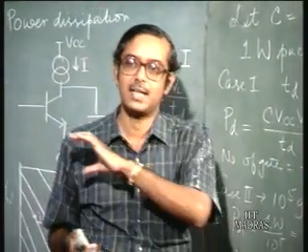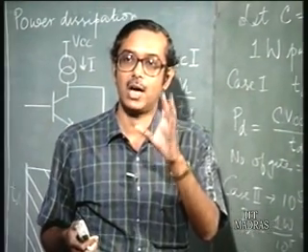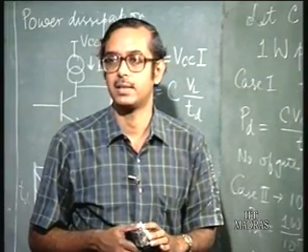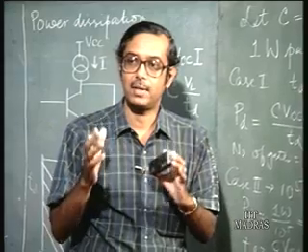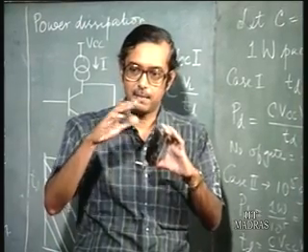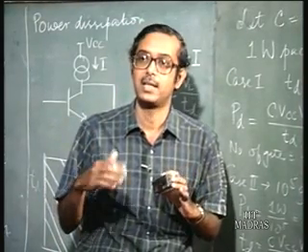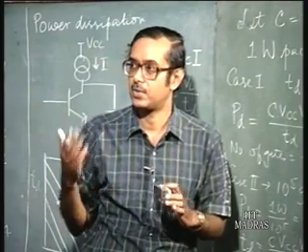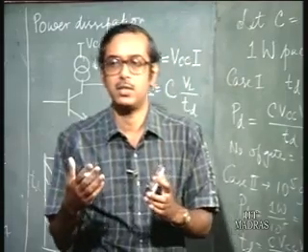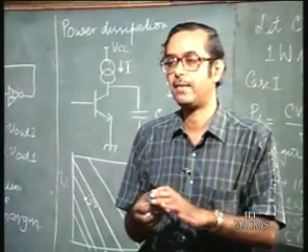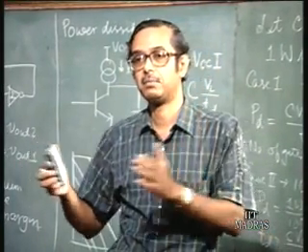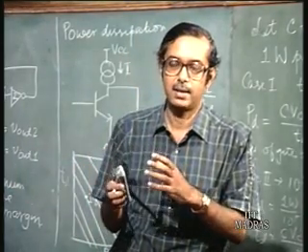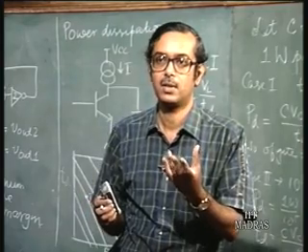So, this gives us the idea of the noise margin: what is the maximum noise the circuit can tolerate. Obviously, if you want to have a higher noise margin, the input output characteristics should be more symmetric. We shall see that as we go along. That is, there is no point having a very high noise margin high and a very low noise margin low, because it is mostly governed by the lower value.